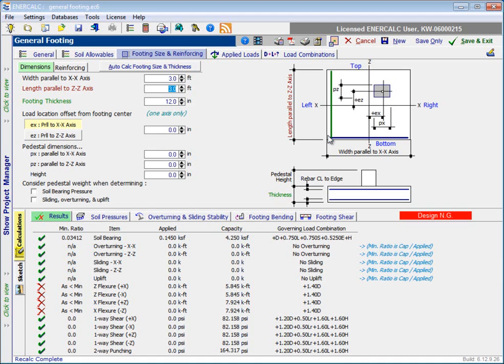So that all coordinates. And then the other layer that's important to understand is that we've named the four edges of the footing. So notice that there is a reference to the top of the footing and the bottom of the footing, not to be thought of through the thickness of the footing, but to be thought of in a plan dimension sense.